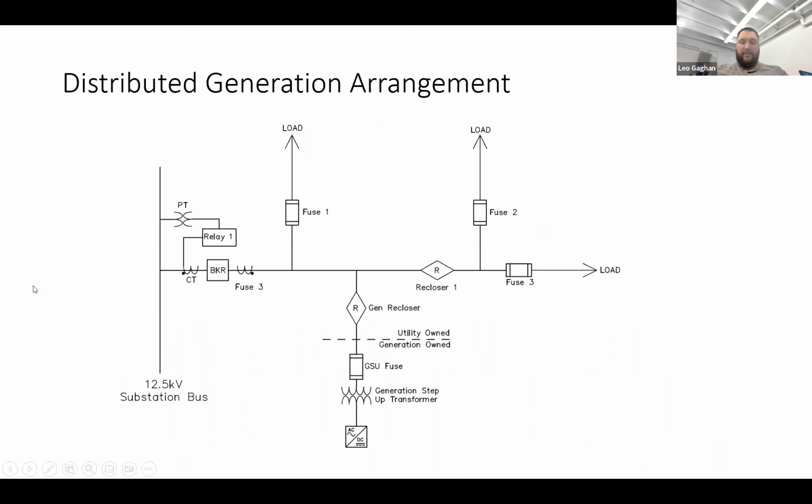So like here, for example, this inverter based generation would not be able to source any zero sequence current out onto the system. But if we were to make this a delta 600 volt side and a Y grounded 12.5 kV side, it would be able to source zero sequence current out through that neutral of that transformer. So as far as what goes out onto the system, the fact that it can't produce a zero sequence current, it's not that big of a deal.